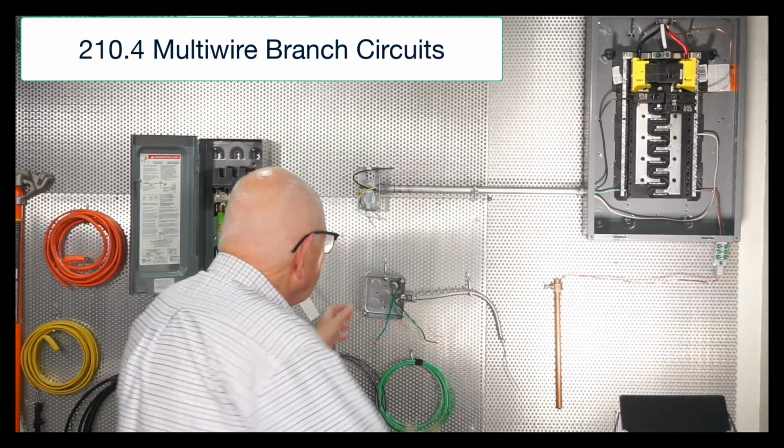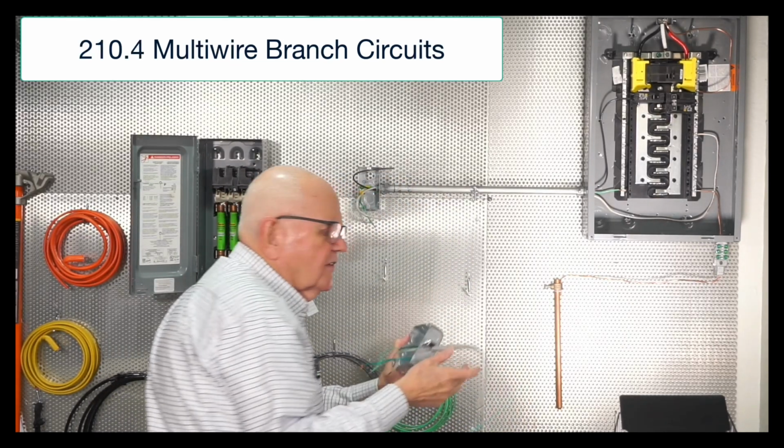If there is an exception, okay, it's pretty obvious. For instance, let's take this one. Let's say I were using this type MC cable in order to supply this outlet. And let's say it were a multi-wire circuit. It's pretty obvious, right, when I attach this MC cable to my enclosure up here for my panel board, it's going to be obvious where all those conductors are coming from. So I would know that those conductors are coming together. So when all my conductors are in the same cable or same conduit, I don't have to group them together by putting that cable tie or cable marking or whatever. So anyway, an exception for that.